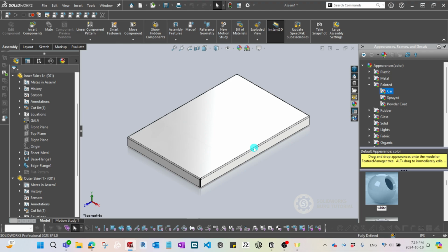Once you set up correctly for the inner and outer skin, when it comes to assembling, it is so much easier because the plane starting point and everything is pretty much the same. So you can assemble or mate by plane to plane, and clean things up. That's so much easier. So when it comes to creating another size of the panel, you can just save as, and then pack and go, whatever, and reuse those templates. But we're going to touch on those things a little bit more deeply in the future. So for any kind of modular design, this is perfect for utilizing this template approach.